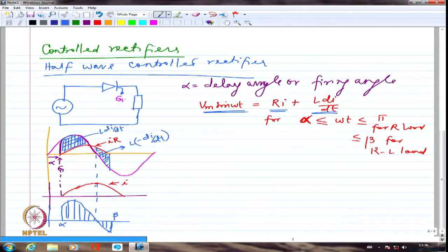So I have to essentially solve the complete differential equation, look at the regular, the particular integral, and then I should be able to say at what point, that is, the initial condition will be I of alpha equal to 0. And the final condition, beta, can be solved for by putting in the same solution I of beta equal to 0, and solve for beta.